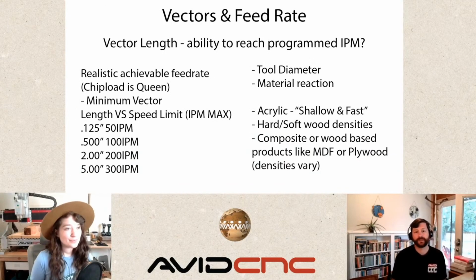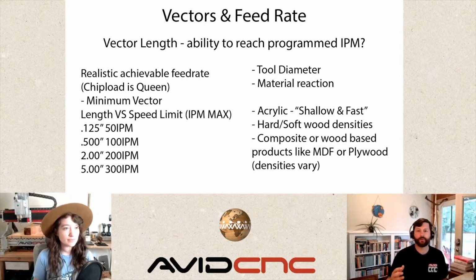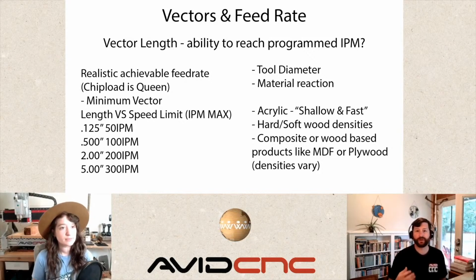Definitely. Yeah, so the next thing we want to talk about here is vectors and feed rates. What I try to focus on when I'm creating tool paths is the chips. I am trying to set the machine up to make perfect chips. And so I always consider my vectors when I'm assigning feed rates. I want to make sure that I am setting the machine up for achievable feed rates so that my chip load is calculated correctly.